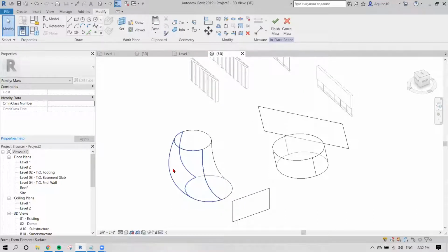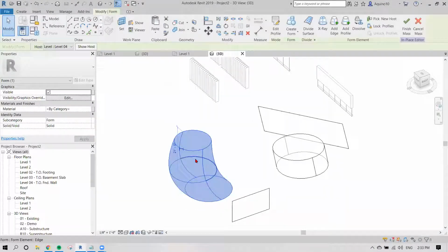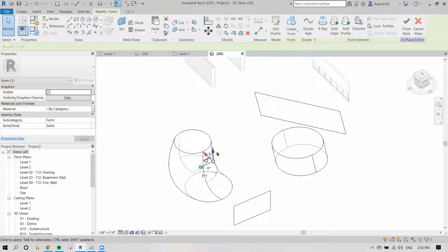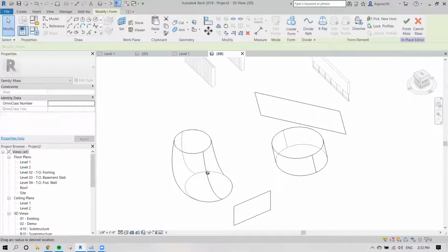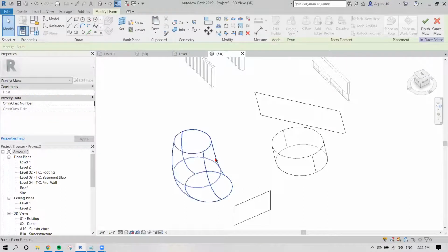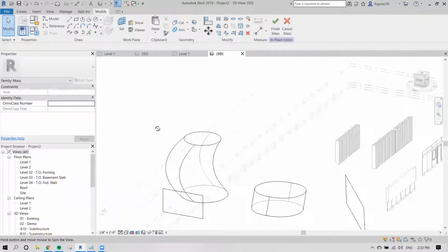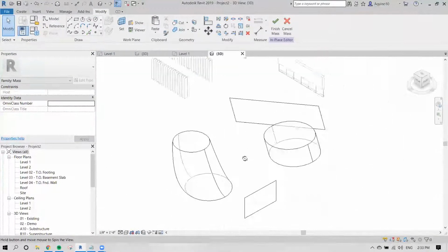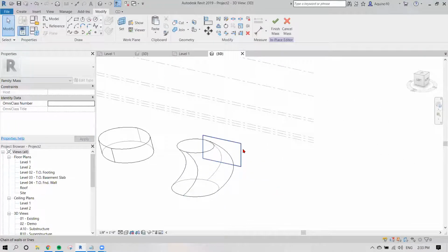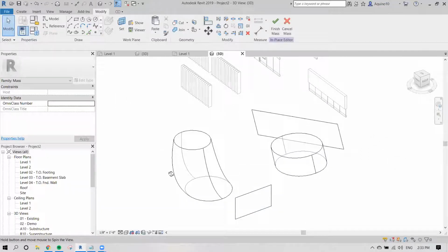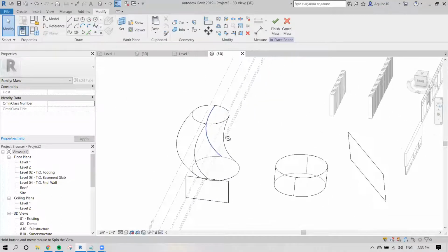And these can be updated on the spot. So if you select the curve, again, this gumball-like tool shows up, and then you could translate it. You can rotate it, etc., scale it slightly. So you can have double curved surfaces now generated in Revit, as opposed to having to make it in Rhino and import it in. This is a really easy process.